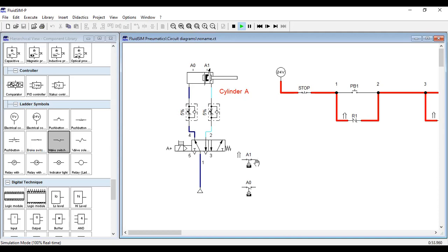That's why we use the concept that when the sensor detects the position or the operation or the status of the cylinder, it closes. Okay, so it's actually open, but as it detects the status of the cylinder, the sensor closes its contact.